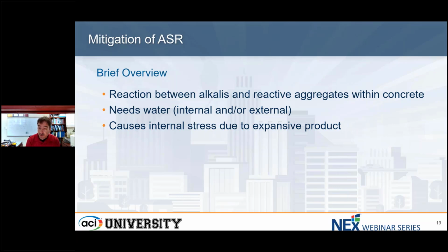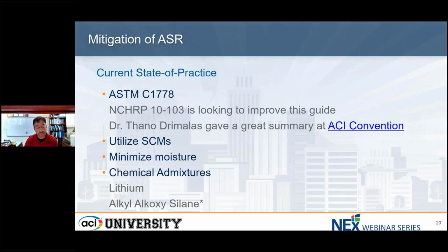Several mitigation strategies over the years have focused on that by essentially saying, okay, we'll protect the surface of our concrete so water doesn't continually get into it. So that's a good avenue for mitigation. Not always applicable for every type of project. And the reason we don't want it is that when it forms this gel, the gel is expansive, causes a lot of internal stress, and our structure starts cracking a lot, which is not good.